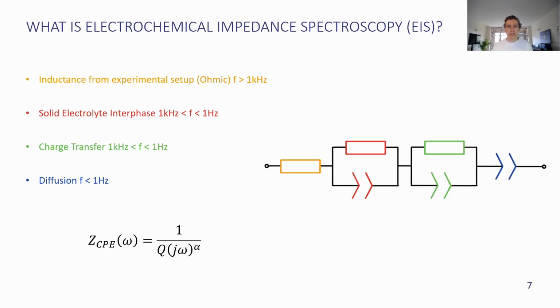So typically, a constant phase element is described as an imperfect capacitor, because although batteries display capacitive behavior, they are far enough away from a perfect capacitor that a perfect capacitor just isn't a good model for it. And so the constant phase element models an imperfect capacitor by adding the little alpha subscript to its equation.